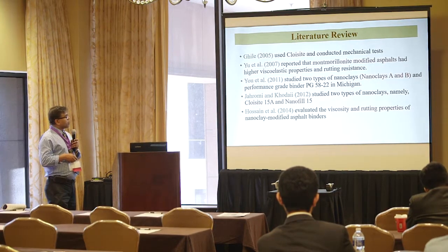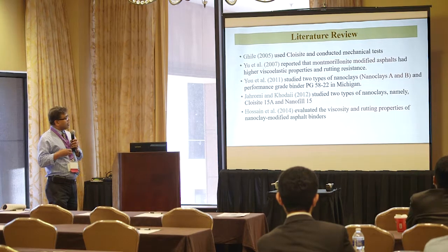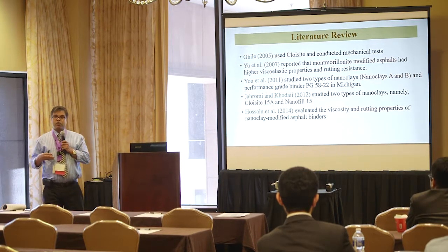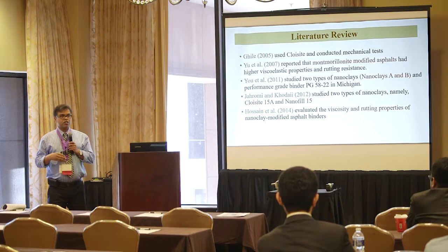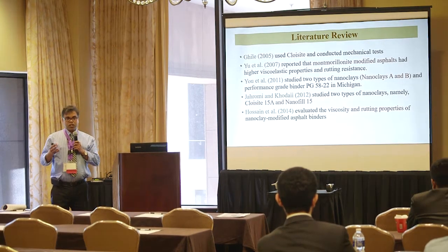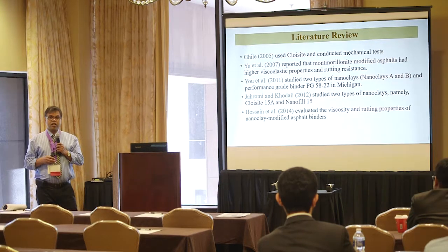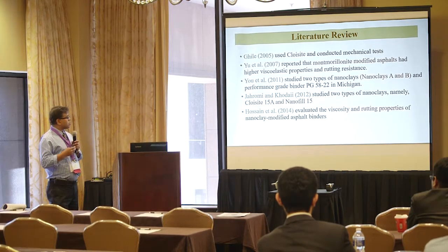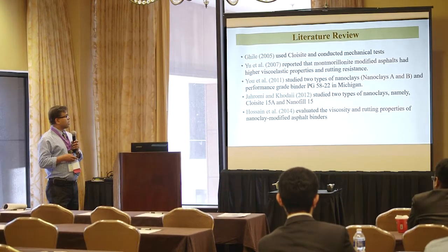And the majority of them have shown that nanoclays improve the rutting performance, that it increases the stiffness. Once you have a higher stiffness value, that means it is harder. It is going to give you more resistance to rutting. So that is the majority of the research that they reported.